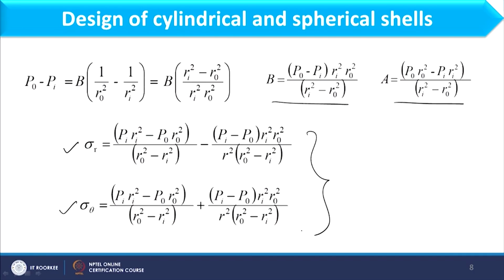Now, if you consider these two equations, both internal and external pressures are acting simultaneously. However, when we operate the system, it may be internal pressure operation or external pressure operation, but here we will derive the expression for the internal pressure condition. So, when I am considering the internal pressure condition, it means the external pressure would be 0.